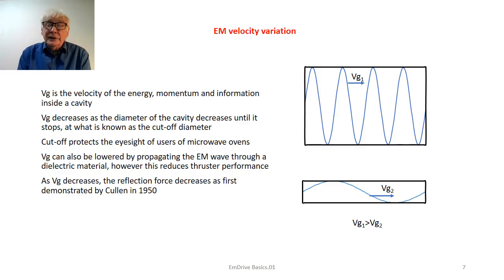The diameter of these holes is well below the cutoff diameter, and they prevent the microwave power inside the oven from leaking out to the kitchen. If this didn't happen, I'm afraid we'd all be walking around with severe cataracts in our eyes. So cutoff is a real situation, and it's one that we must take account of in the design of an EmDrive cavity.